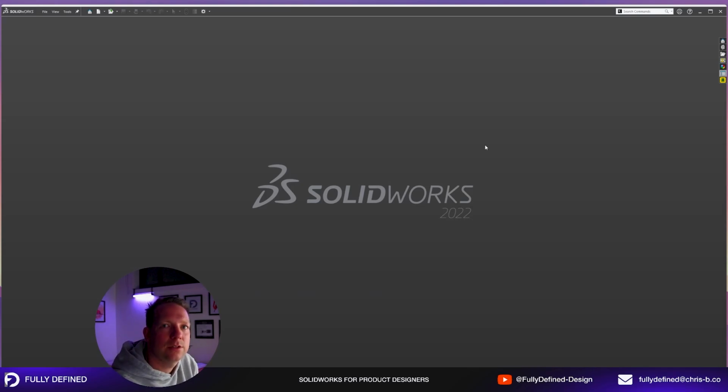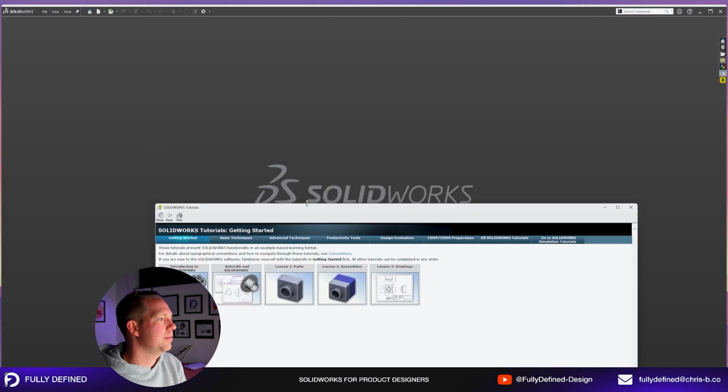Right, when you want to start the tutorials, all you need to do is open up your SolidWorks, find the question mark at the top of your menu bar. Now, it might be different depending on your version. I'm in SolidWorks 2022. In this, tutorials are hidden under the help question mark in the top right corner. I click that, and click on tutorials, and it brings up this screen.